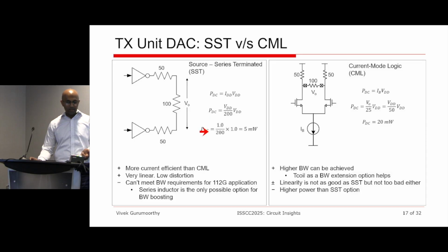And obviously, yes, right? It's just an inverter-based DAC, so it's extremely linear. You're switching from 0 to 1 level all the time. So this has pretty low distortion, but it has some other disadvantages like bandwidth limitations, which we will go through soon. The current mode logic DAC is slightly higher power, but the linearity is not as good because